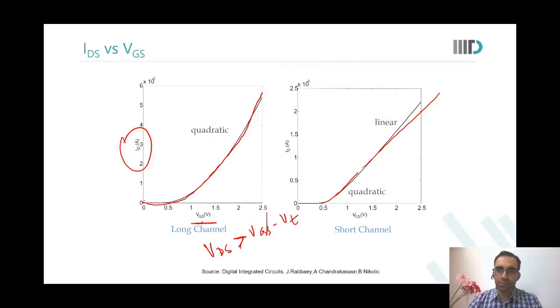I was asking, sir, in older technologies, when we were not going to very low voltages, the sub-threshold current would not really be something we were worried about, right? Yeah, in older technologies, VT was also very high, 0.7, 0.8 volt. So even if the slope was bad, the leakage current would be low. Additionally, the total number of devices you could put on silicon was also less, so total leakage never bothered us.